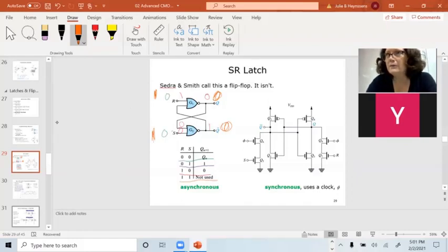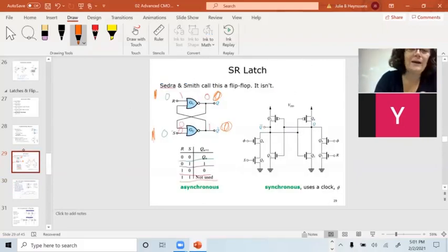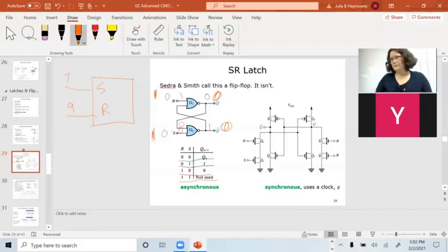I just avoided using that state and used my SR flip-flop because I didn't want to deal with the JK toggle thing because I didn't understand it. So how did I avoid that state? I had my SR flip-flops look like this. S was going to the output of a counter, and the output of the counter would decode state 7 of the counter. So it would only go true when state 7 was true. And R would only go true when state 9 was true. That way they're on separate states, and 7 and 9 cannot be true at the same time.